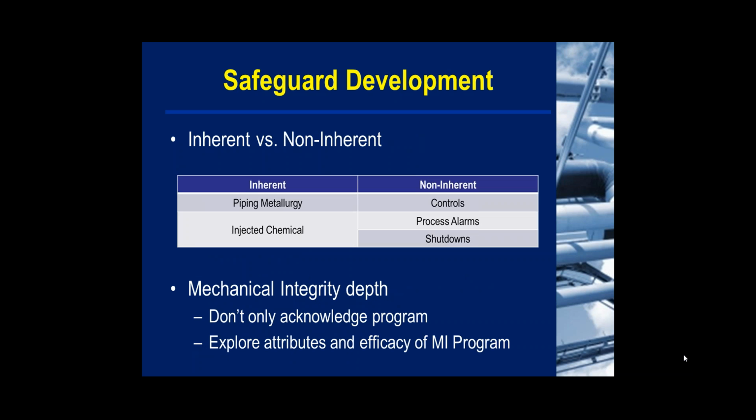And instead of passing on to the process engineer to provide a detailed description, we recommend passing off to the mechanical engineer and metallurgist to provide that description and include the details of the piping and equipment metallurgy, as well as operating parameters and other contributing factors to the damage mechanisms in question.